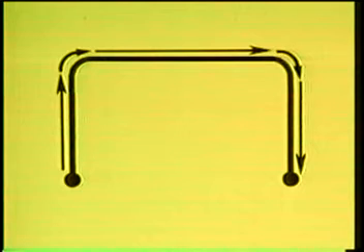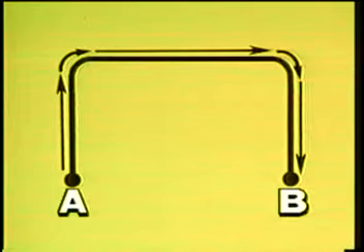To begin, let's define continuity. Continuity is the existence of an uninterrupted current path of low resistance between 2 points. In this diagram, you can see a continuous path between point A and point B. Continuity tests are used to locate broken or burned out connections, common connections or shorts, and to check the bias of diodes.